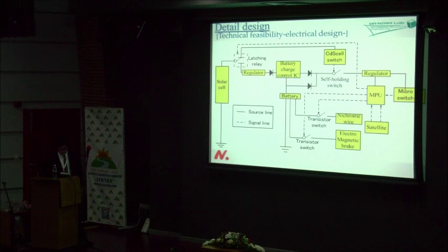Furthermore, the MPU switches the connection of the latching relay so that the solar cell is connected to the regulator that is connected to the battery charge controller IC. Thus, the electric power generated by the solar cell is supplied to the MPU. As a result, the battery is always almost fully charged and the MPU is always turned on. Also, when the MPU receives the signal for standby from the satellite, the MPU resets the time count.